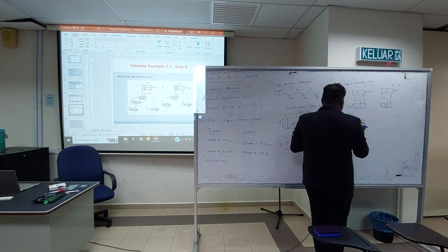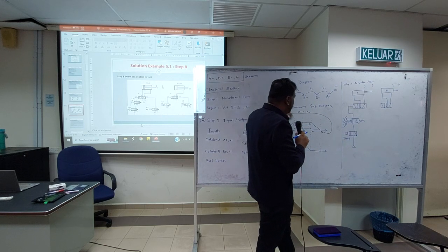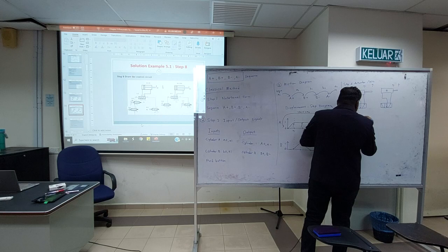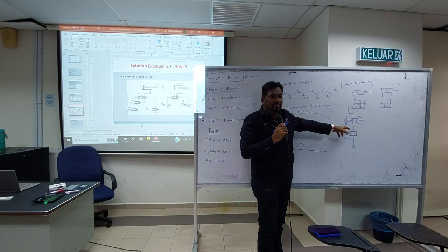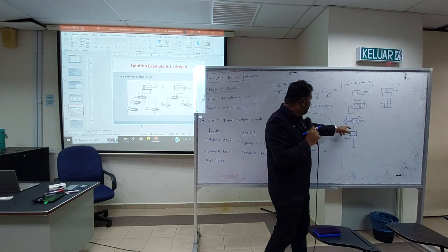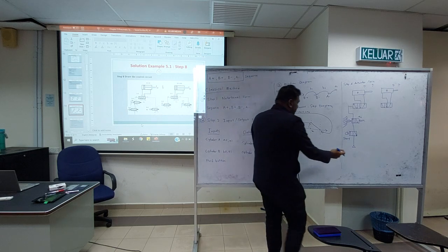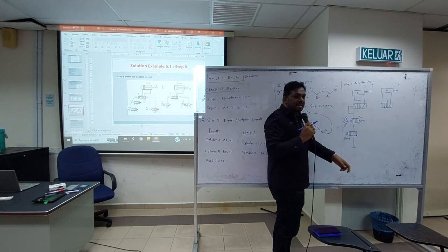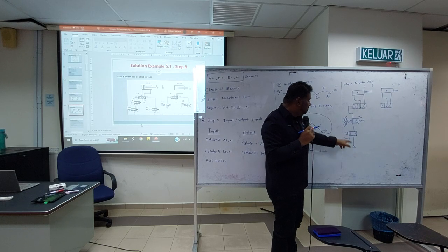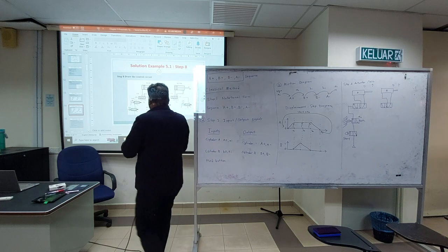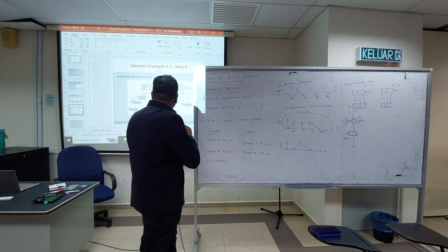So this is your condition: start button and also A0. Do you know how to draw this? Don't know? Okay, so this is the condition. So start and also A0. First you will start from compressed air. So this is the compressed air. Then the push button. The push button is like this. So it will be connected to the unactuated.